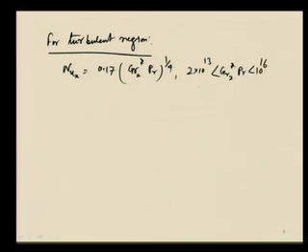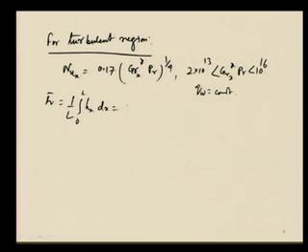So, this is the range, and we know Q_W is the constant wall heat flux case. Now, from there we can find the average heat transfer coefficient, h bar, which is equal to 1 by L times the integral from 0 to L of h_x dx, and this becomes 5 by 4 h_x at x equal to L. We can understand that it is a little bit different from the isothermal condition cases.